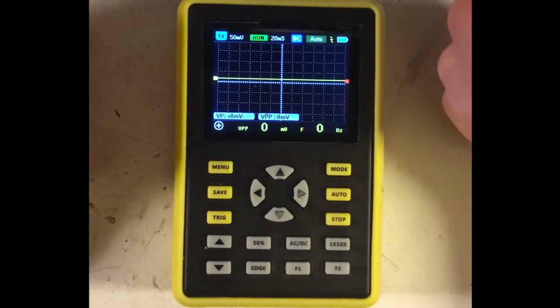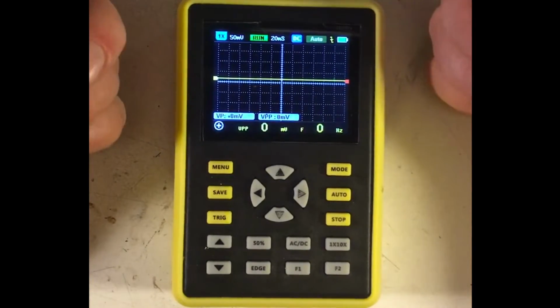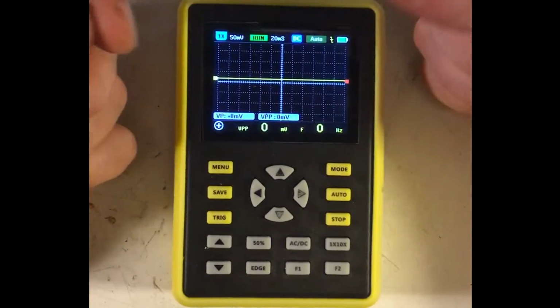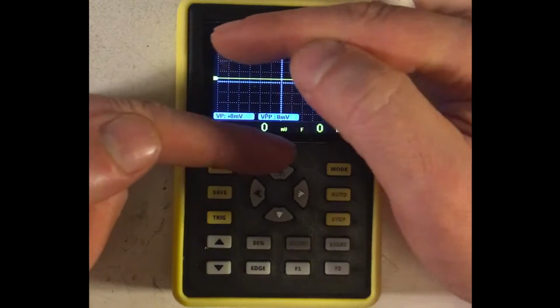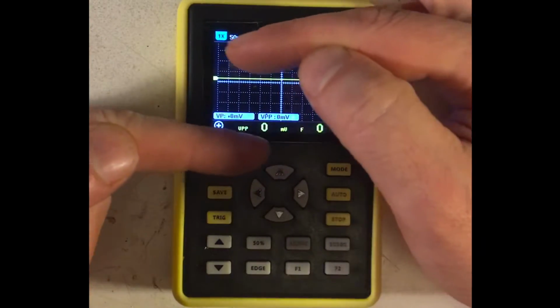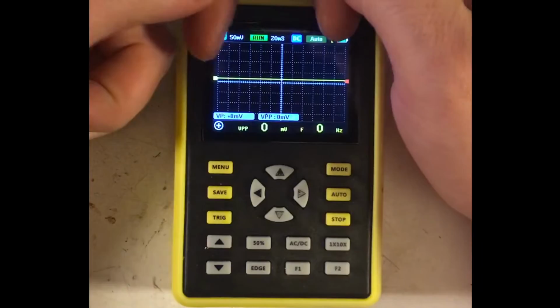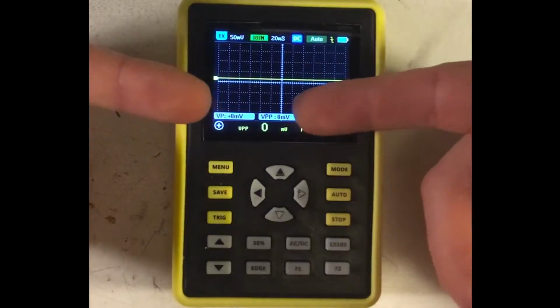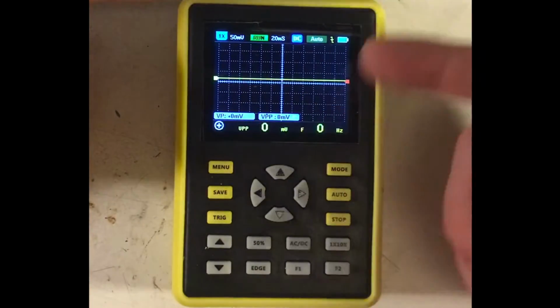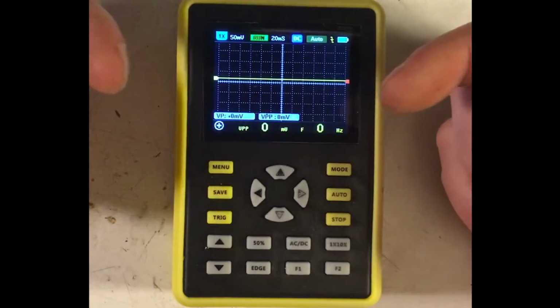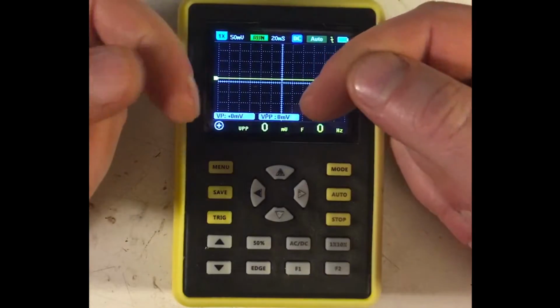And one thing I really like about digital oscilloscopes is when you can have the X and the Y cursors that you can actually move to measure the amplitude and the wavelength, as opposed to just trusting the automagical stuff, because that depends on a continuing cyclical pattern. But if you have something that's uneven, it's nice to get in there and be able to measure it.